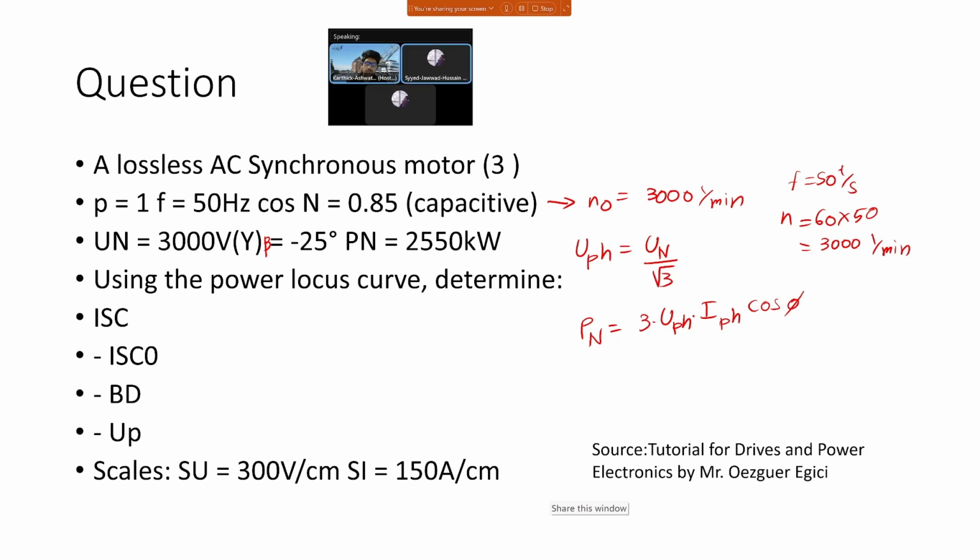This is very well suited, which is why I think trains and such, the newer ones, are using synchronous motors, because then you have perfect control over speed. But naturally, this means you need a proper control circuit for regulating the speed, and you can't do it just through changing the load itself.